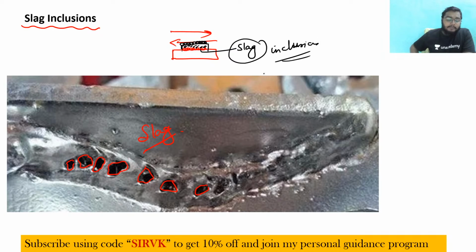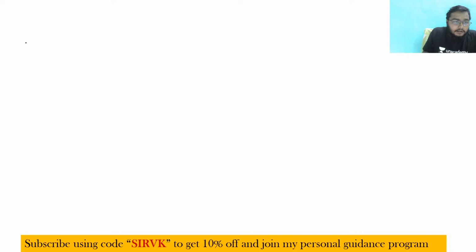So due to lack of proper heat input, or improper positioning of the welding torch, or if you are conducting multi-pass welding, in these kinds of situations we get slag inclusion. Okay, so let me write it here, my dear friend.